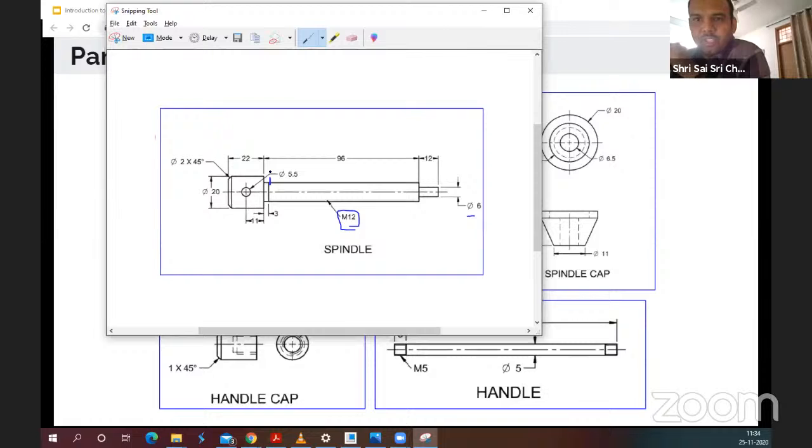It is a very common practice for manufacturers to develop threads, and it is also fed into the CNC. So they can just select the shaft, give the pitch, and refer to the standard. That does a better job so that we do not mistakenly give the wrong pitches or grooves, because the mating nuts and other things are already industry standards.